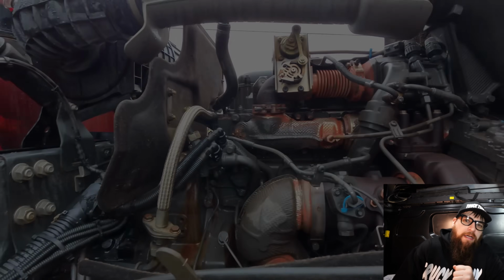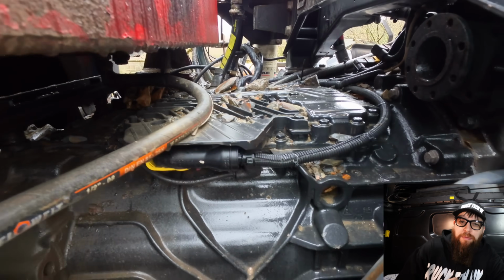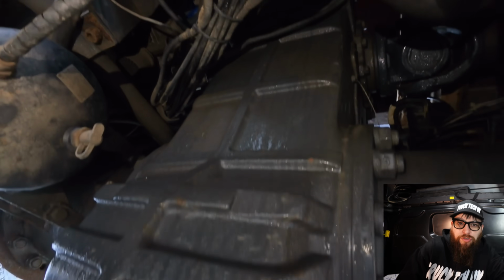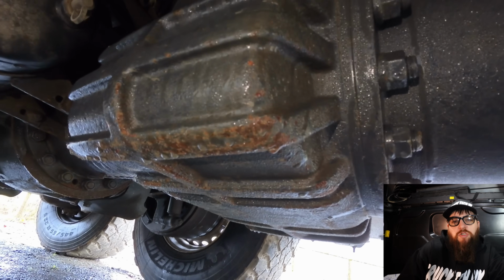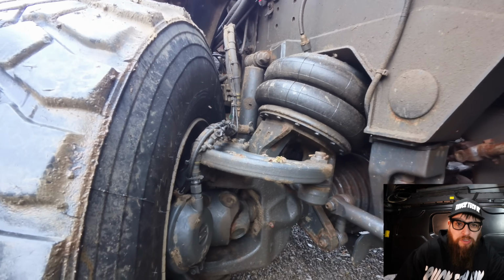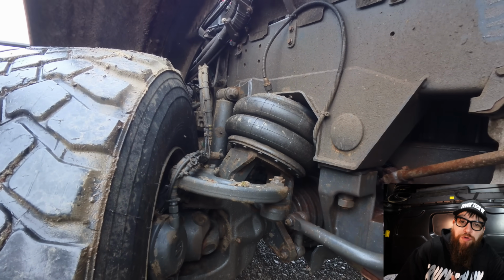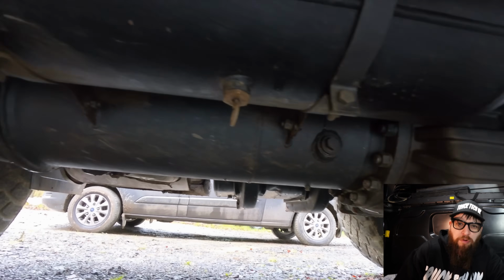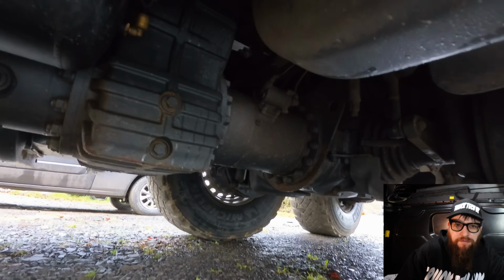Now we might have a Paccar engine, gearbox and cab, but the transmission after the transfer gearbox is Tatra's own construction, with the independently suspended swinging half axles and air suspension. It's all bolted up to this central load carrying tube. Is your head spinning yet? Mine certainly is, so I've borrowed these pictures as it's quite a feat of engineering.